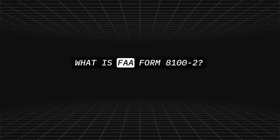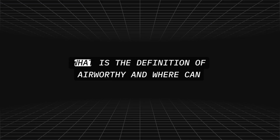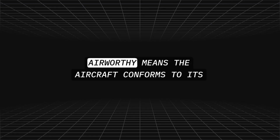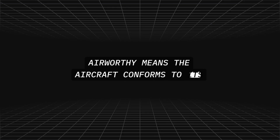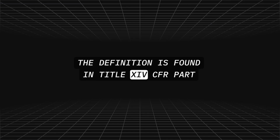What is FAA Form 8100-2? It is a standard airworthiness certificate. What is the definition of airworthy and where can it be found? Airworthy means the aircraft conforms to its type design and is in a condition for safe operation. The definition is found in Title 14 CFR Part 3.